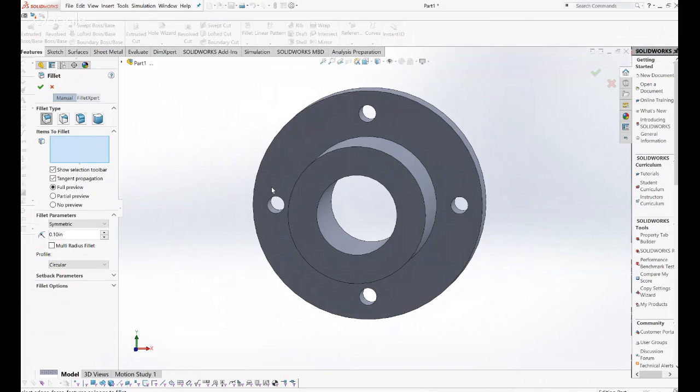They also serve a purpose solid mechanics wise, which you'll learn in school, where they get rid of stress concentrations if your part is going to be feeling a lot of forces in angles. So it has 2 purposes. For this part, since it doesn't feel a whole lot of stress, we're just going to use it so the machinists have a much easier time making it.